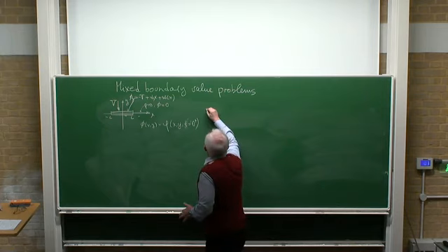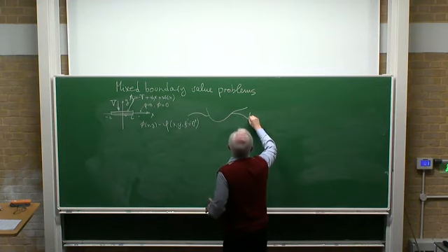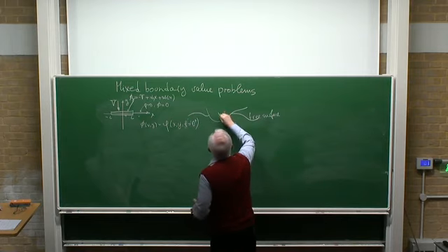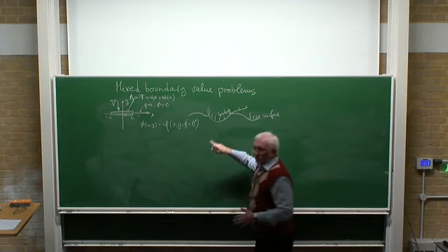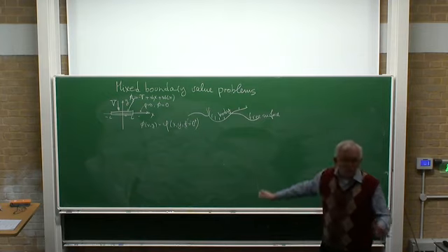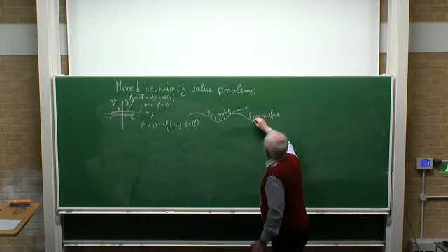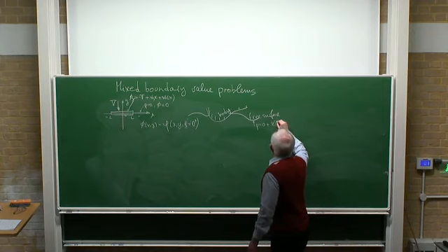Any problem with a free surface, let us say free surface, and that is the body surface, that is the body. In each problem, they exist for ships or any others. On the free surface, the boundary condition is for the pressure, pressure equal to constant, plus the so-called kinematic boundary condition.